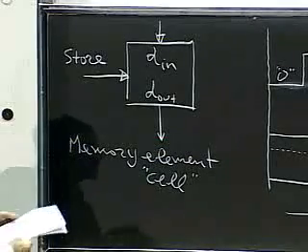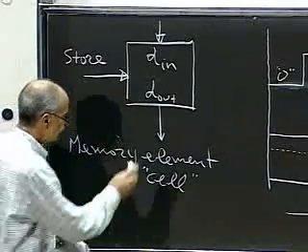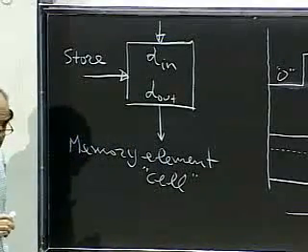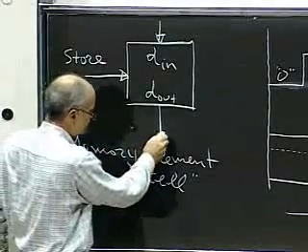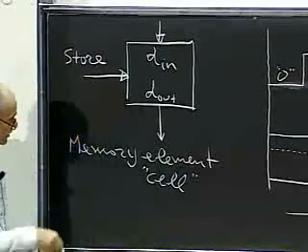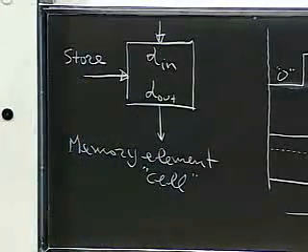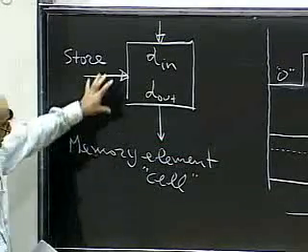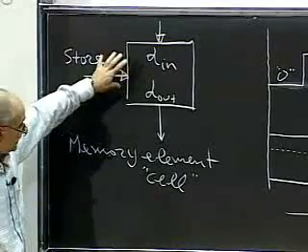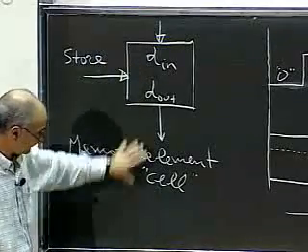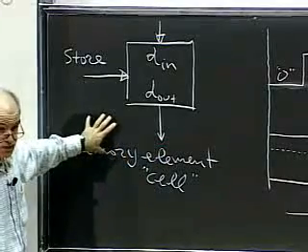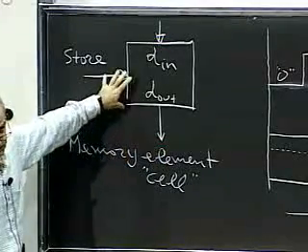And not only that, but in principle, it should be undisturbable, okay? In other words, I may do something to this D out, but it should not flip the state. And that comes about quite a bit because in actual integrated circuit memory, there's lots and lots of nearest neighbors to this cell, which, when they're flipped, have a cross-coupling to this cell.